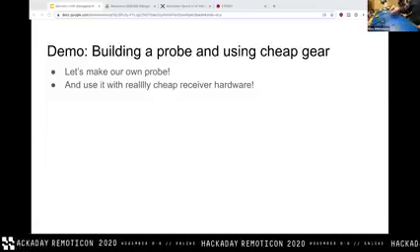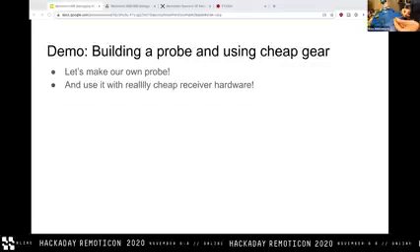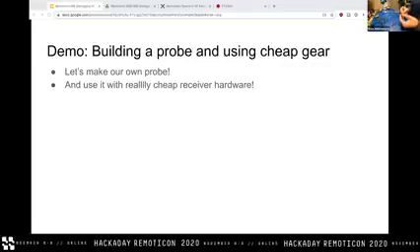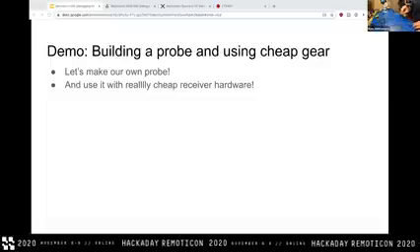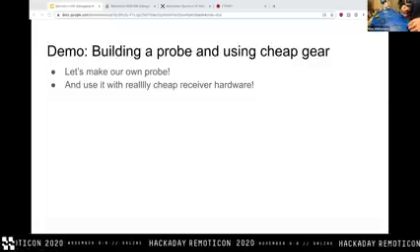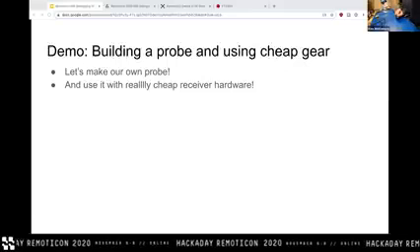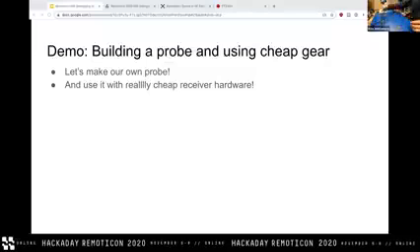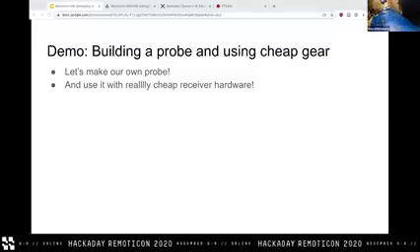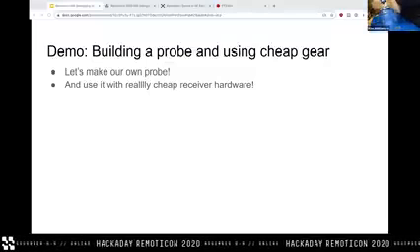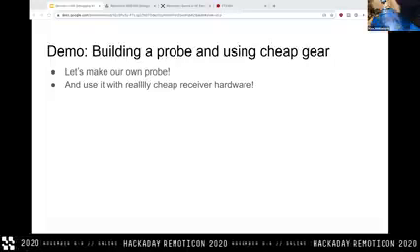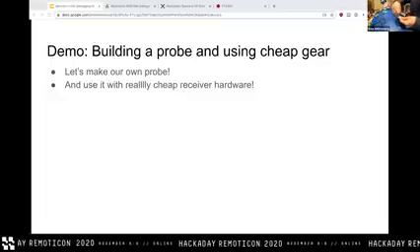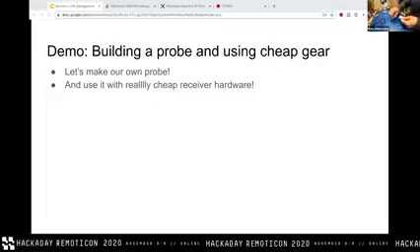So the way I made this probe, obviously it's magnet wire and an SMA connector just taped onto a regular garden variety wooden skewer. I've got my magnet wire here. What I did was, I originally wound this on a pin, but we'll just grab some sewing needles out of my thing instead.